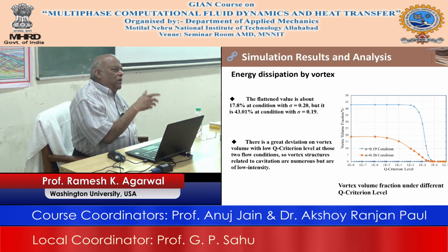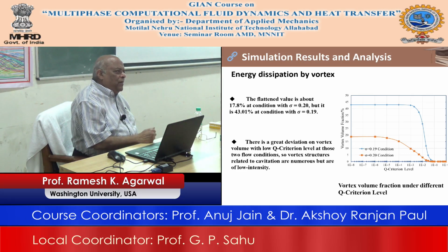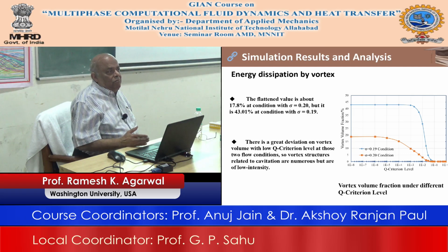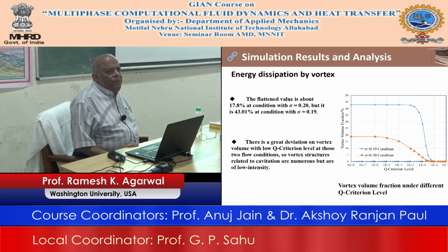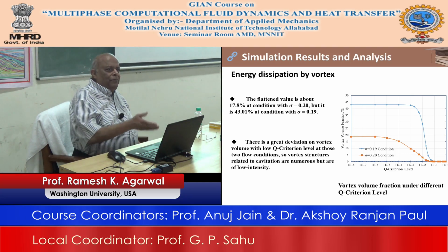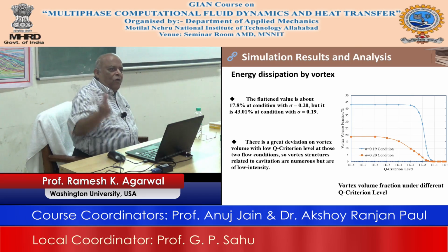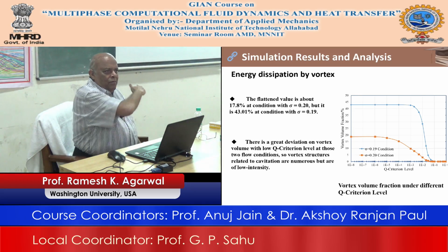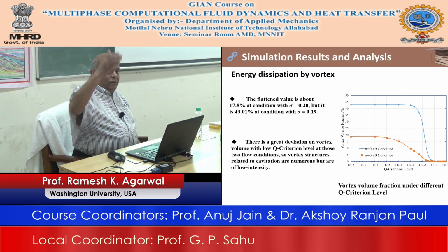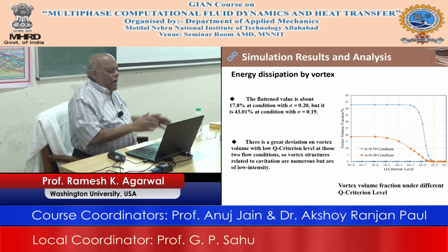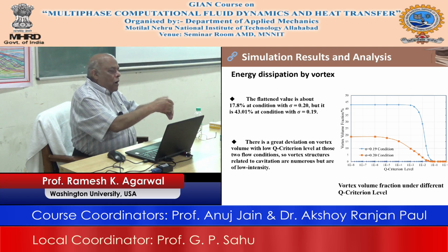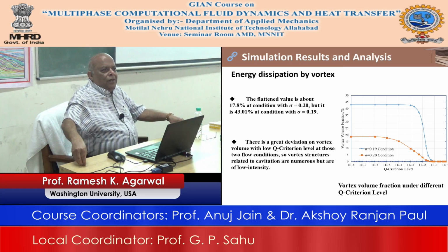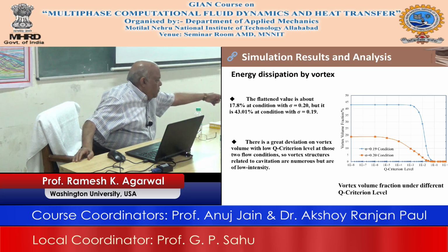But the other very important thing I think you should get out of this is how to characterize the vorticity. All right. If you want to use this, just take the boundary layer on a flat plate, which is full of profiles as you move, changing profiles, because there is a boundary layer thickness and therefore the gradient changes. Use that gradient delta U in 2 dimensions to see how Q changes from here to here. So suppose the flow is coming from that side, what is the boundary layer thickness there?